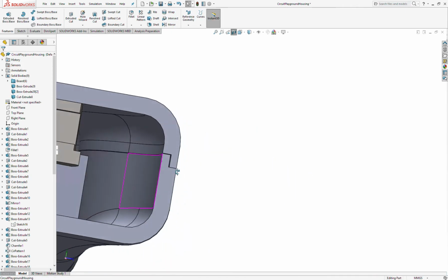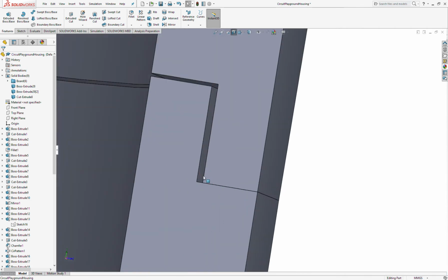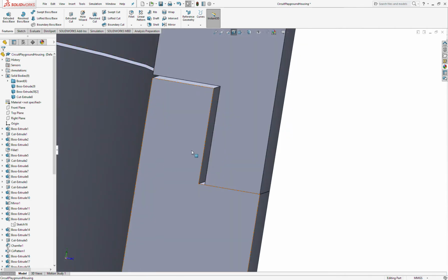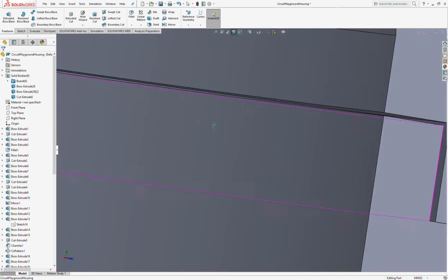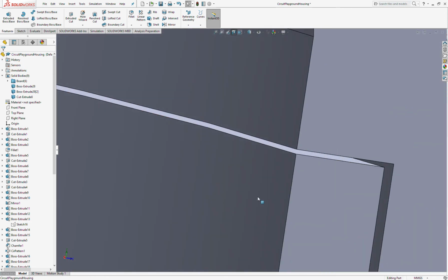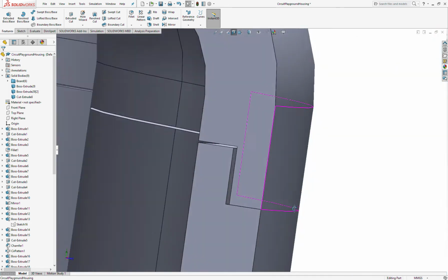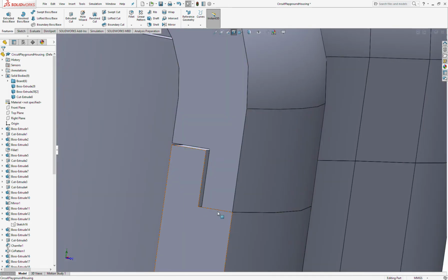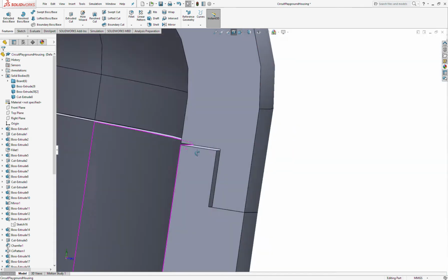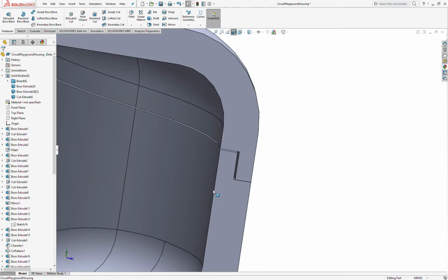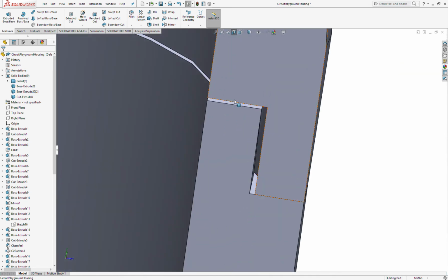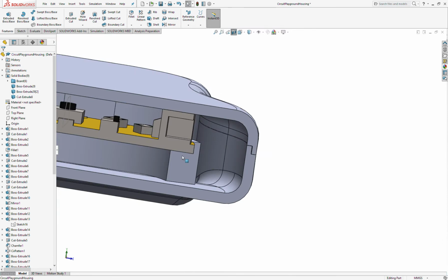So looking at the section cut, when we see how this fits together, these two surfaces, they're just 0.1 millimeters apart. They're actually going to rub against each other. But the advantage of leaving a little gap there, sort of at the top, is that when these come together, the surface that will contact will be this surface. We can actually do sort of the reverse as well if we want this surface to be in contact, and we can leave a little relief gap there as well. Just sort of how things are going to sit against each other. But having both surfaces contact simultaneously, something might not sit quite right.